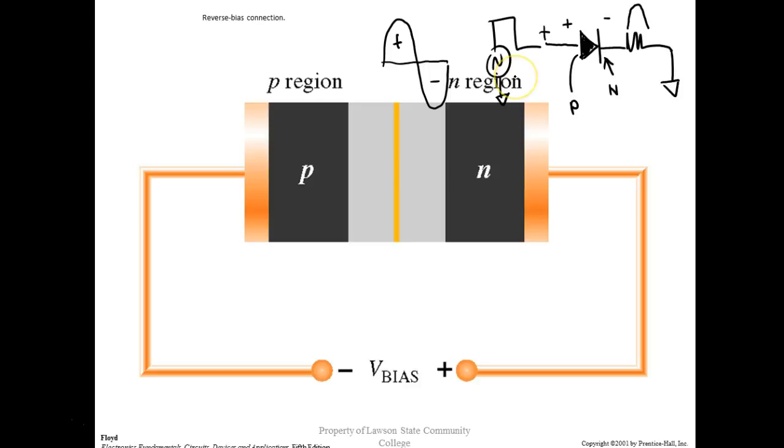It would be 7/10 of a volt shorter because before it conducts, we had to exceed the 7/10 of a volt. During the negative polarity, this becomes negative, this becomes positive. The diode turns off. So I'd get nothing here. What I would get across my resistor would be this right here.